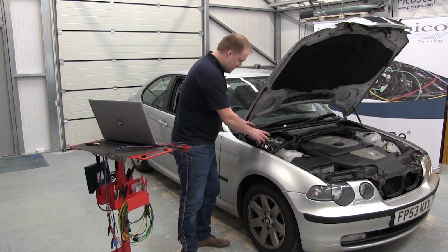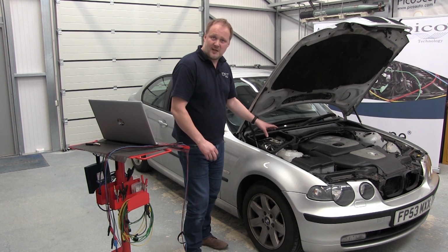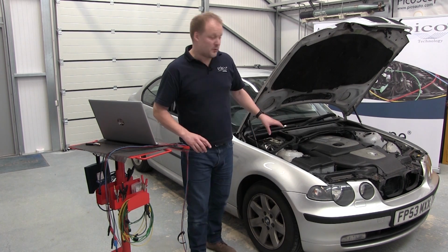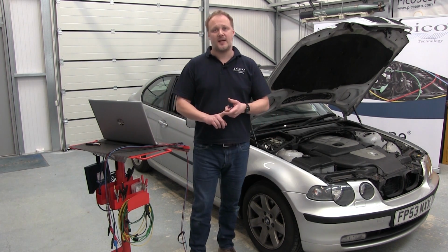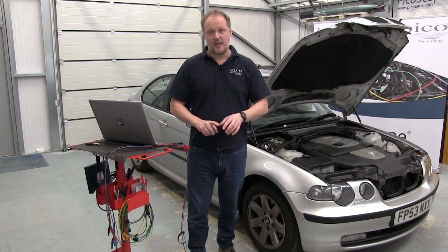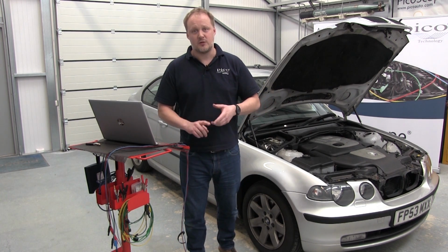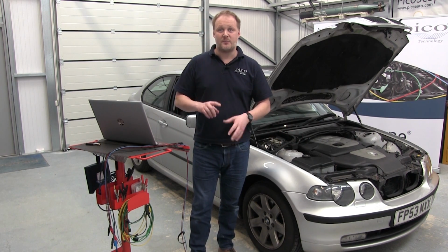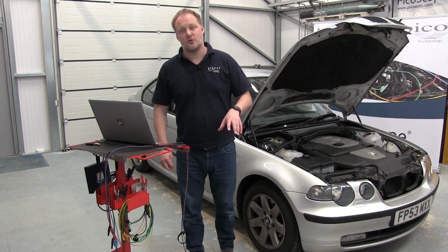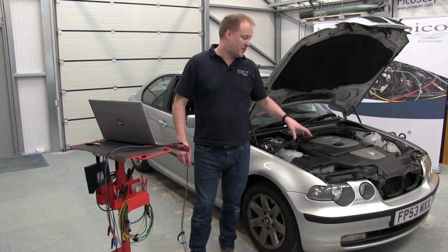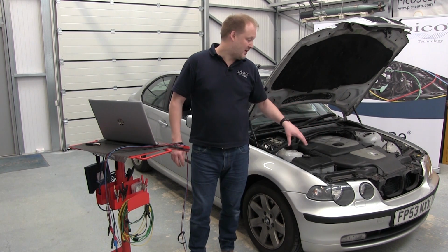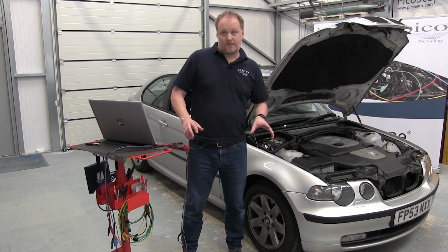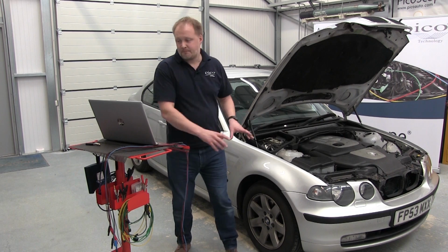On this vehicle, we've got an ABS control module, really nice and available close at hand here. That will give us access to the high-speed CAN network, and on that we'll have the engine control module, ABS control module, instrument cluster, if it's got it, a transmission control module, and even adaptive headlamp modules, plus of course a steering angle sensor. So plenty we can look at.